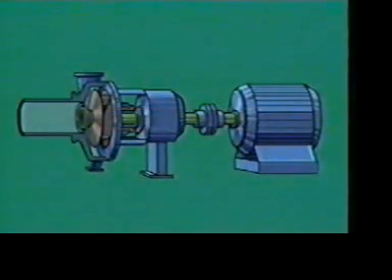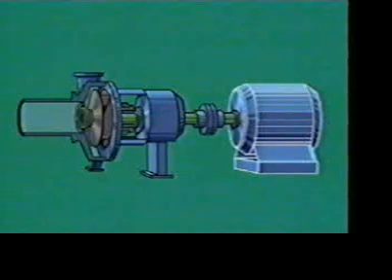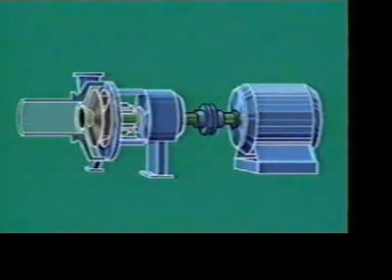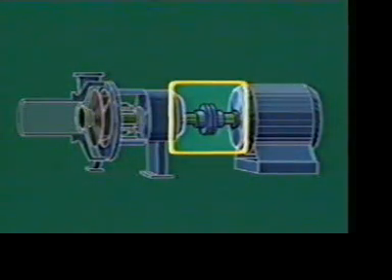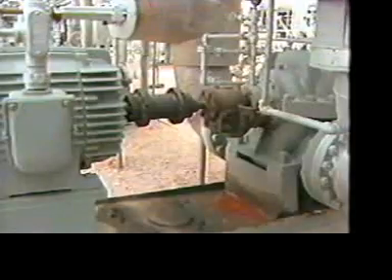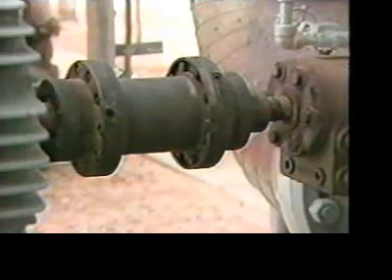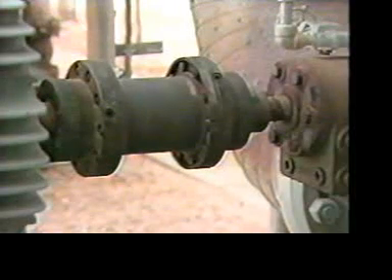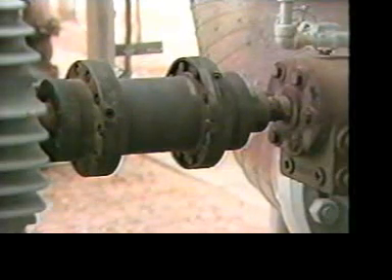Let's stop. Here's the driver. There's the pump itself. What links them? This, the coupling. It connects or couples the driver to the pump. And it does so for a purpose: to transmit power from the drive shaft to the pump shaft. Although they might seem simple, couplings are as critical as all the other components. They've got to be strong enough to withstand sudden changes in the pump's load, and also those times when the driver might stop.